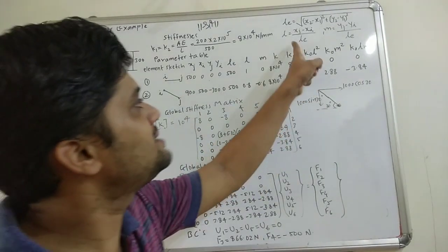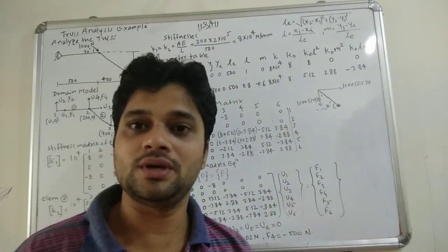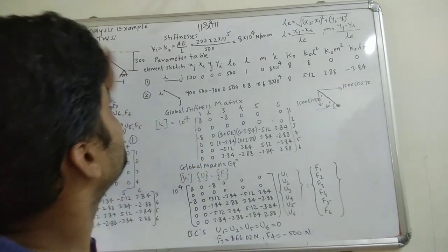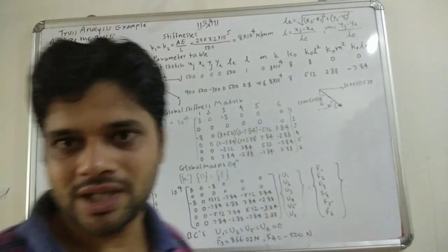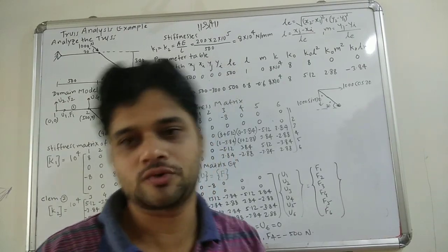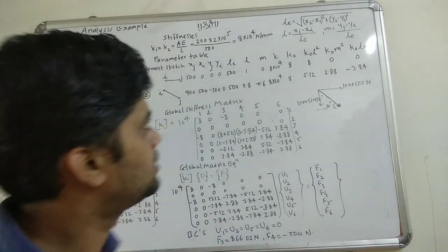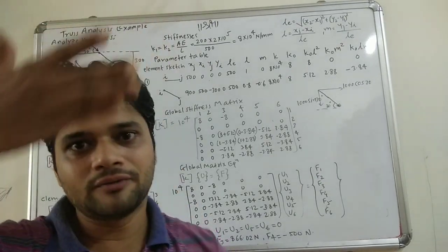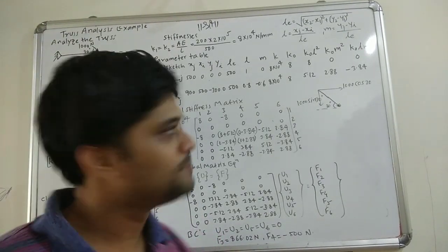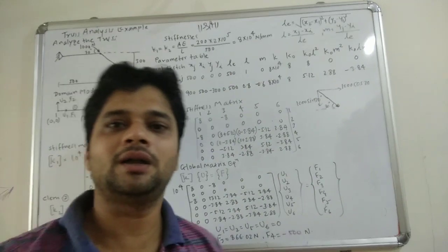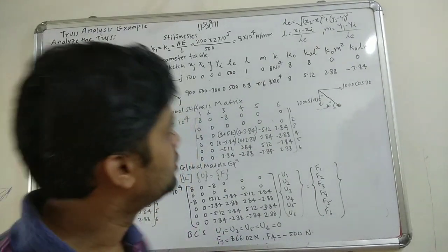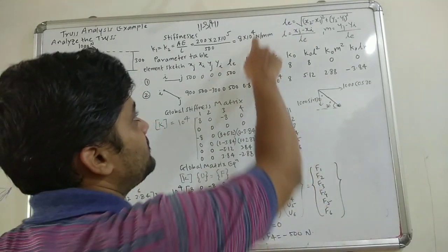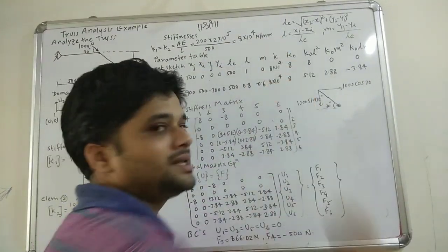Now the next thing is K0. K0 is the uncommon factor from the stiffnesses. Fortunately for us here, we have the same stiffness values for both elements. But sometimes, if there are 2 or 3 elements, you may have different stiffness values, so you will have some common factor and some uncommon factor. So K0 being the uncommon factor, what is the common factor we are considering? The common factor is 10 raised to 4.